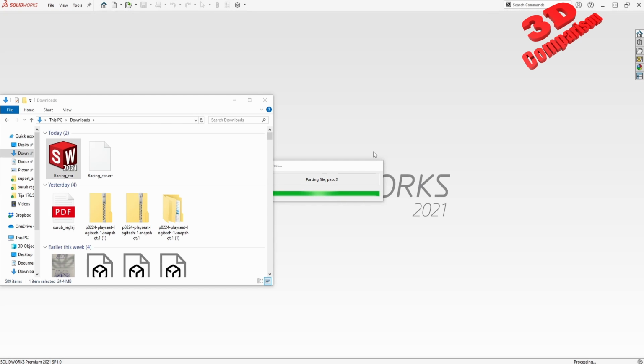This is also one of the, let's say, differences between CATIA and SolidWorks. We see how long it will take for SolidWorks to open this STEP file in comparison to CATIA. And there are also some key differences. SolidWorks will unpack all the parts within this existing folder, while CATIA will be able to process that without having to unpack that STEP directly over here where the file is. So I'm currently gonna wait for SolidWorks to convert this.